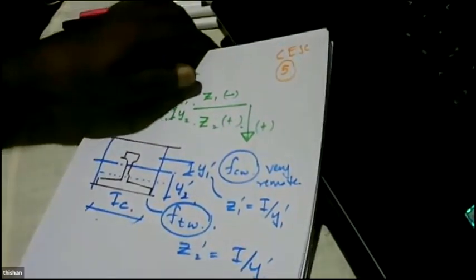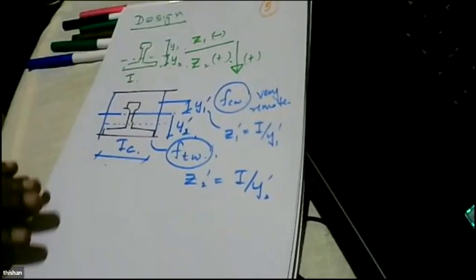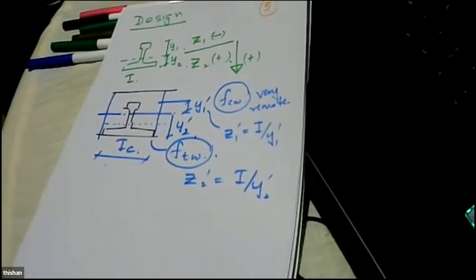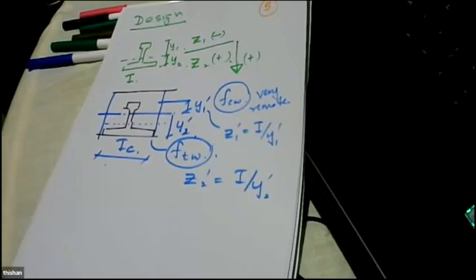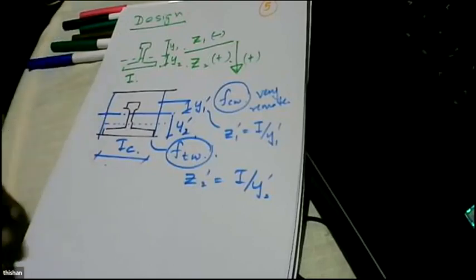So this is something again you have to be pretty certain about, because here you have to understand that once the composite action becomes effective, what you are changing is the neutral axis, but we are not changing the section. We are still designing a pre-stress concrete section, so the section cannot change.